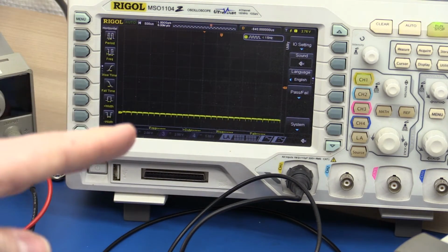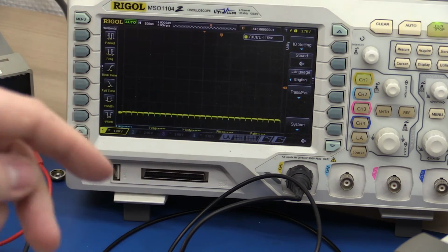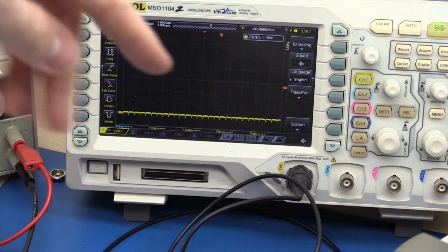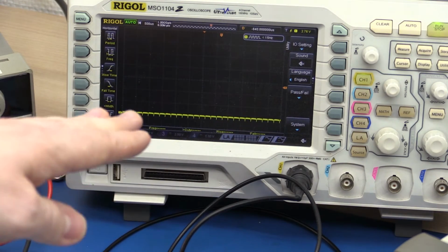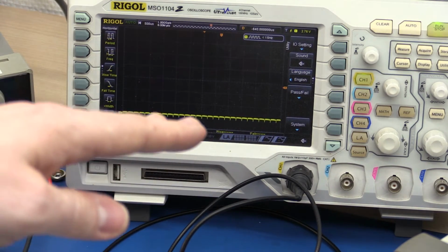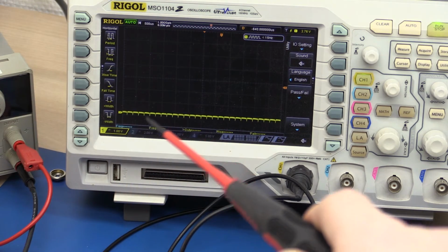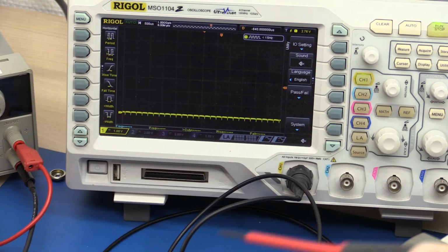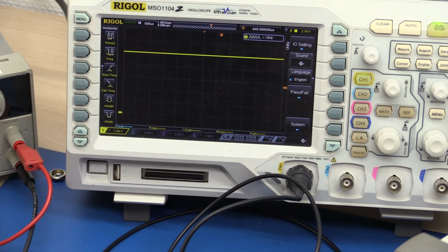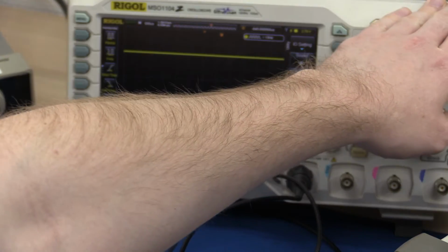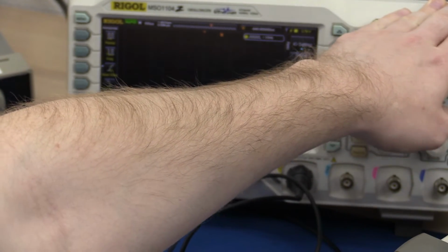So what we expect to see now, as the slope rises, is an ever increasing duty cycle. Now you can see it's low, so we expect the end result to be 100%, and in between we want to see an increasing duty cycle at the frequency set by the sawtooth generator. It's probably difficult to see when it's rolling like this, but let's make a single capture.